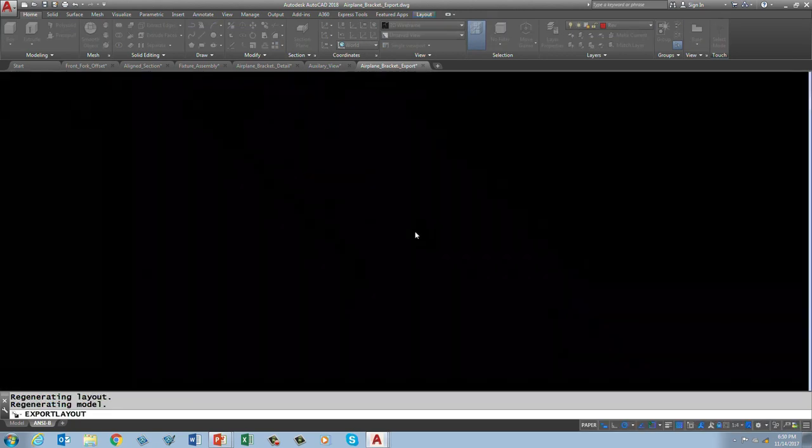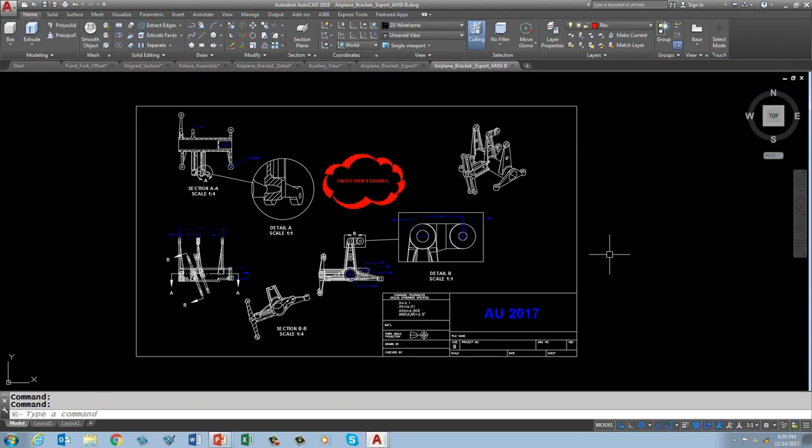And then AutoCAD should ask you to open it. And there it opens with all the dimensions. Everything that you did in that layout will now be in model space. True size, true shape, 1-to-1. You can go in and dimension it now if you would like, modify the layers, reset the layers, and now bring this to your website to be able to do that. See that? And that's it. I mean, that's how simple it is to bring that over.